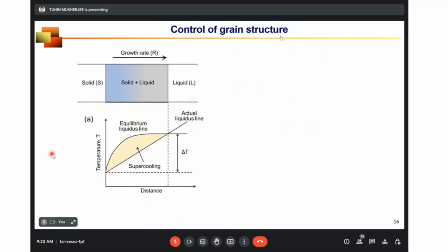So now let me give you examples of how the models and machine learning can be used for controlling grain structure, properties, and defects. Now, as we know, in additive manufacturing processes, solids are formed from liquid, like any other process such as casting or welding, and so on. But for alloys, solids do not form directly from liquid. There is a two-phase region, as we see from the phase diagrams, solid, liquid, mushy region.